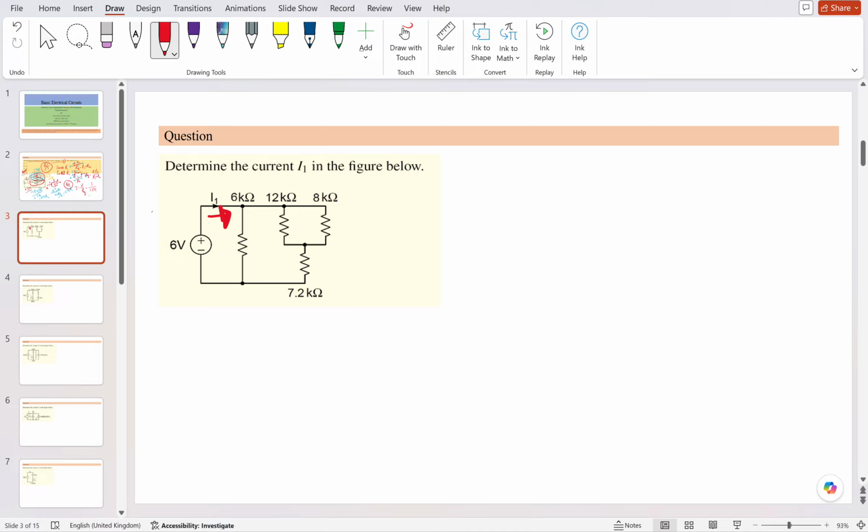Okay, I got multiple answers as 1.5 milliamps. Whoever solved and who have not solved, just listen here. If you see the network, whatever the topology is, you just have to observe what kind of reductions are possible in that circuit. Either series combination, parallel combination, or a combination of these, or star-delta conversion can be possible. So you always have to try to reduce the network, to make it easy to solve the currents and voltages.